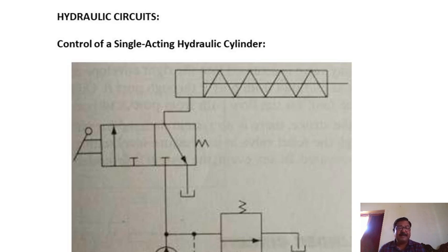And also the main units and parts of any hydraulic circuit are the power pack. The hydraulic power pack comprises the main oil tank, and also the hydraulic pump, the electric drive motor, mechanical couplings, and strainers for filtering the oil, and also filters and coolers. In some cases, after circulation in the hydraulic circuit, the oil may be heated up. That heated oil should be cooled properly. Otherwise, it may make problems to the seals.